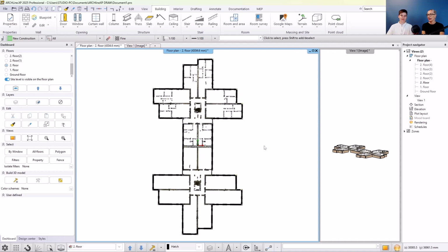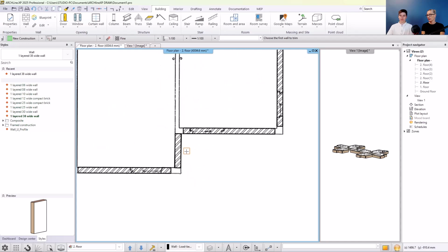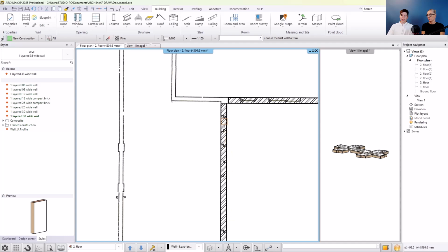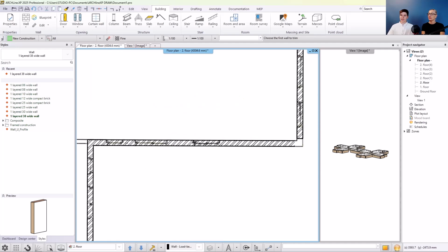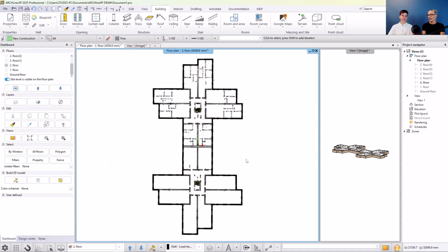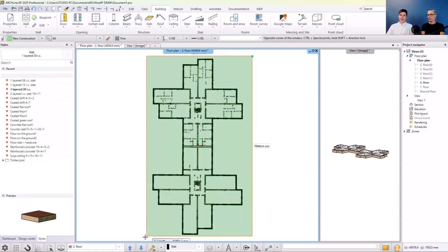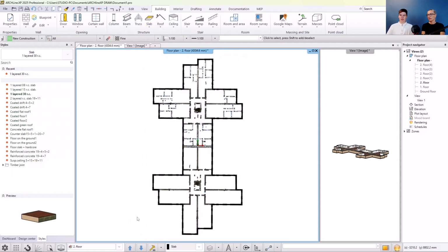How do we connect the finished walls? Use the L and T connections command on the ribbon. Right now I only need L connections. Click on the two walls you want to connect and the software will extend them to meet. What's next? Now I will place a slab inside the area surrounded by walls. Then we will move on to placing the windows.